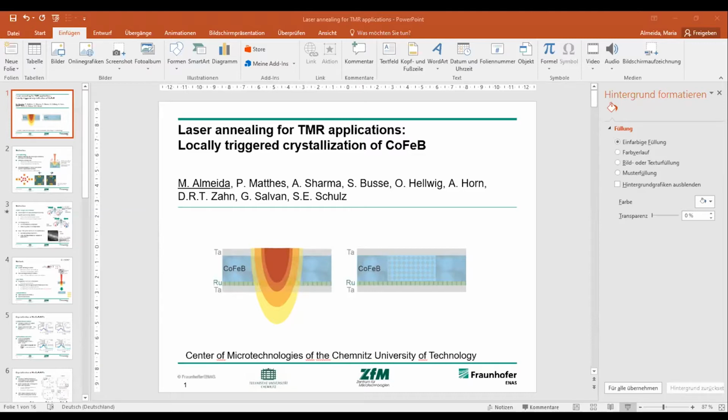As a motivation, we have been working with laser annealing for quite some time now. A lot of focus has been given to setting exchange bias locally, which was proven to be very useful for accomplishing more linear sensors. In the case of GMR sensors, we have published these results where we can set exchange bias in opposite directions to sensors near each other, or even with an orthogonal kind of arrangement to have a two-dimensional sensitivity.